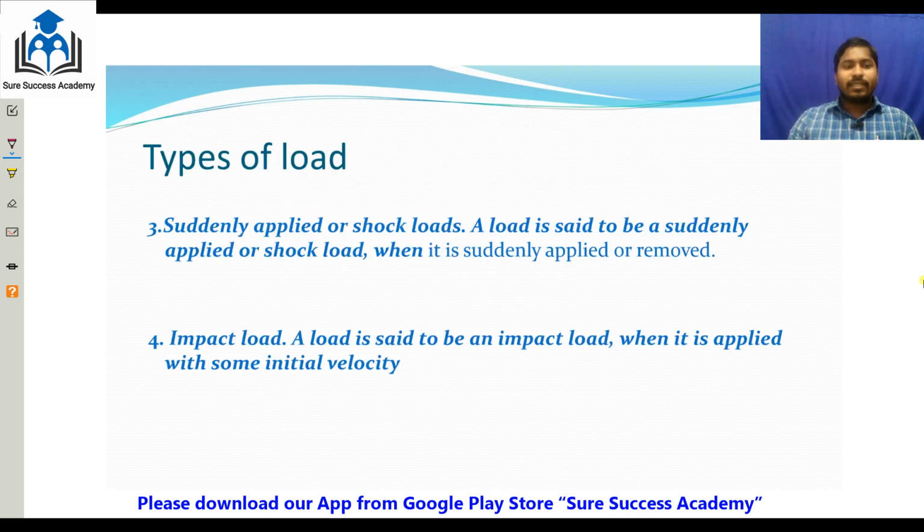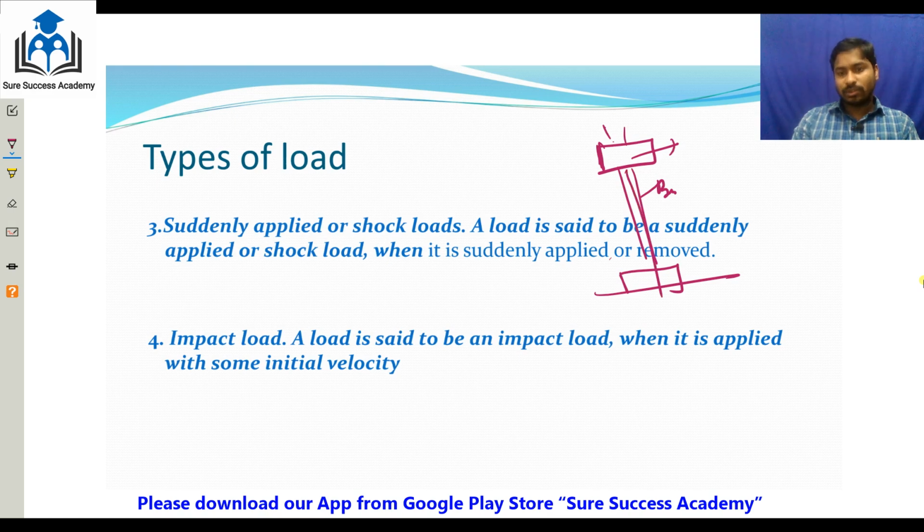Okay. So next, the suddenly applied or shock load. A load is said to be suddenly applied or shock load when it is suddenly applied and suddenly removed. Suppose this is a material, a guiding bar, and we are applying the loads suddenly. It will be like impact loads. Suddenly applied is nothing but the impact. Suddenly, in less time, it will go and strike the bar.